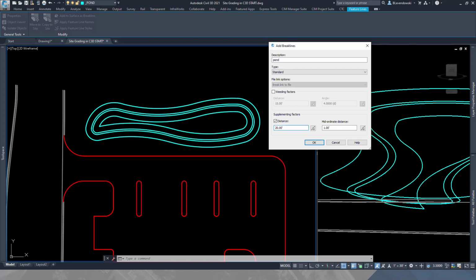It's always going to triangulate where you have a vertex, like a PC or something right here, but say in this parking lot we had a straight grade from here all the way to here. To get nice looking contours, you want triangulation to connect along that feature line. So you would dial that up. What's great in a detailed site grading, something like 10 feet, 15 feet, kind of find a balance there.